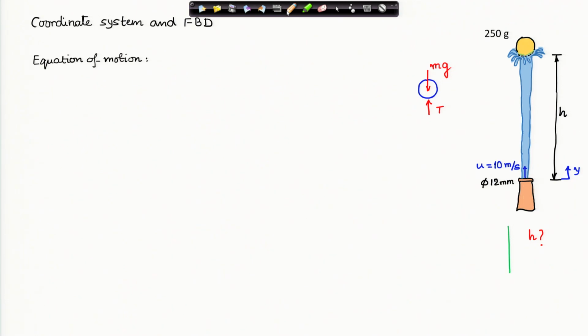The equation of motion we have just now derived, the master equation, I have written out, and then I have struck off the terms which are 0. Mass times acceleration: the system, the ball, is not accelerating, it is held steady. Therefore, the acceleration of the ball is 0, therefore the first term drops out. In the second term, the velocity v is the velocity of the system, which is our ball, which is 0. Therefore, that v drops out.